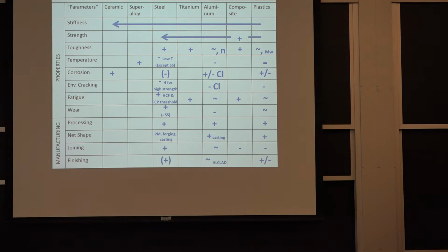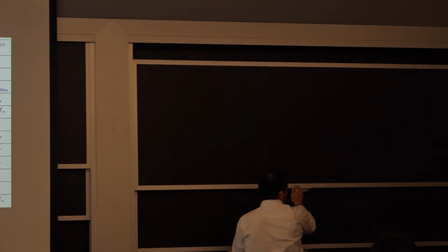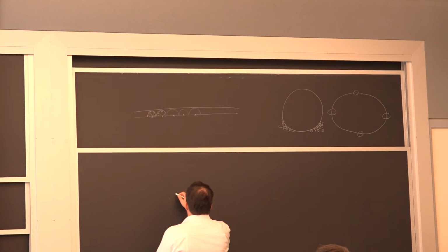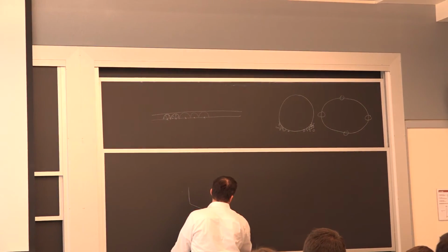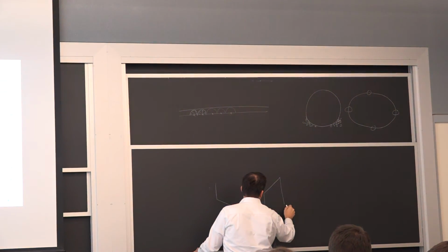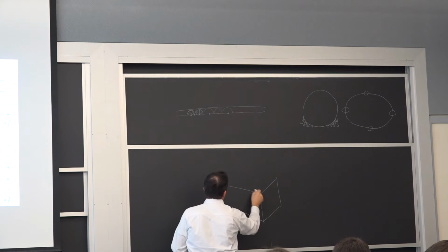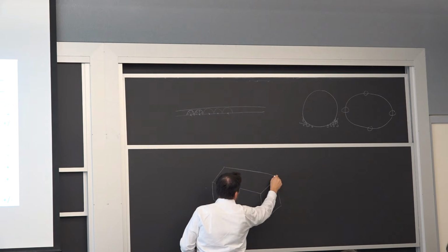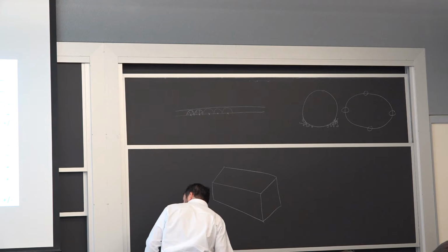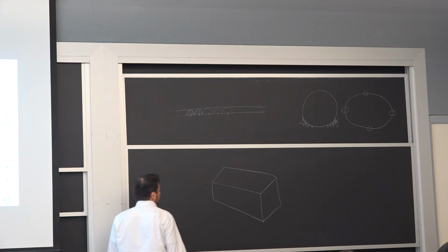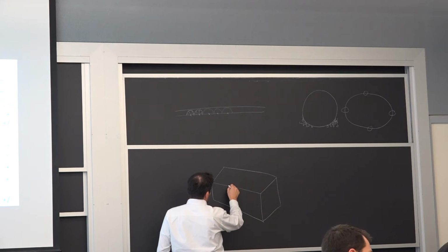I'll just circulate 3 of them. This is the Charpy V-notch test. Anybody know about that? You take essentially a rectangular bar. It's a very standard test, and it's used a lot these days just for, I'd say, qualitative analysis. And you just machine a notch in it.